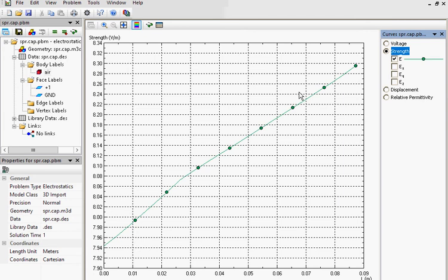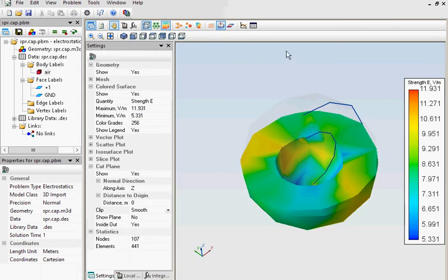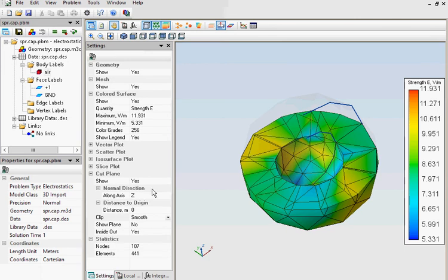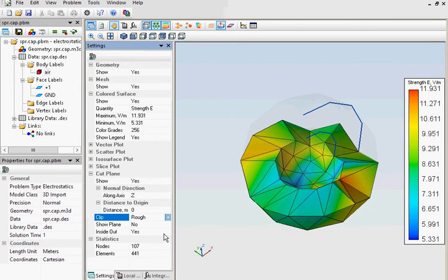Let's take a look at the finite element mesh. I'll switch on the mesh here, half clip. There is only one layer, a linear dependency instead of the squared. Of course we get poor accuracy in this case.